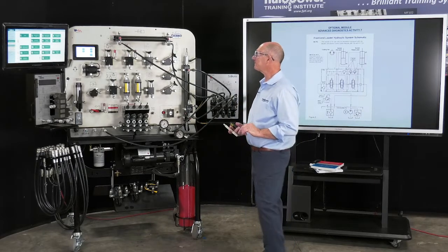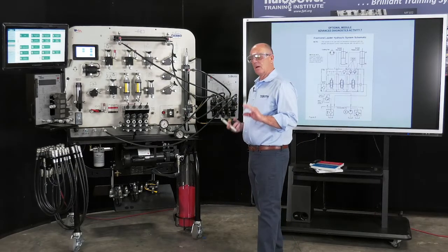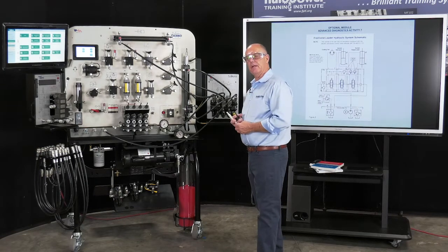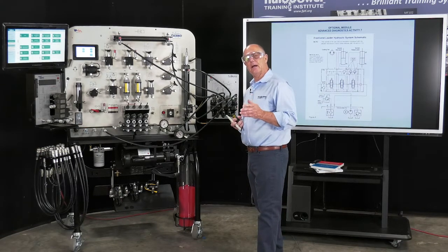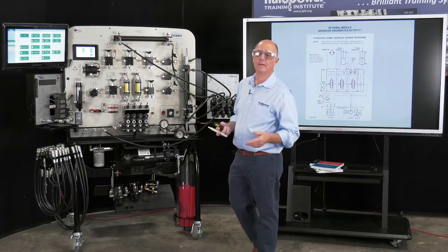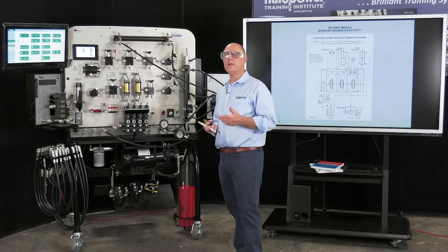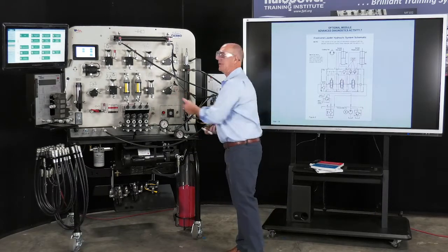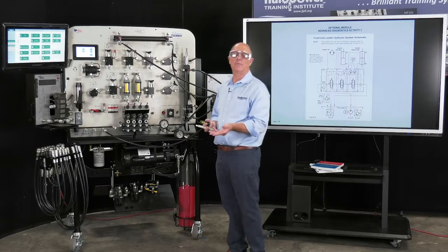All right. Now, what I found as I started to look at leakage rates is that the data in the industry has nothing that tells me when a hydraulic component has reached its terminal leakage rate. In other words, what is the terminal leakage rate for a directional control valve or a pressure control valve?